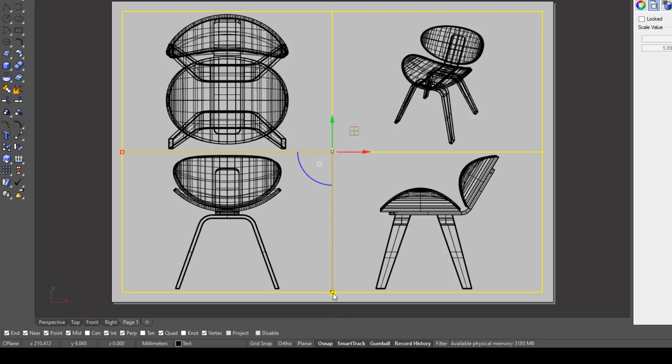And we're going to click on the green square there to scale the height. Just click on it once and it will bring up a size box. So we're going to scale this to 85% of its original size. So its current size is 1. Okay, it's set to like 100%. So to make it 85% of that, we'll type in 0.85.